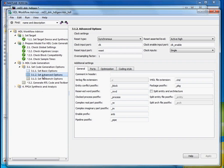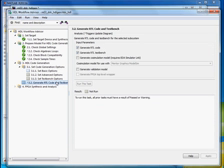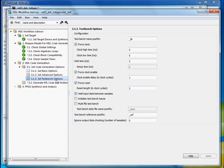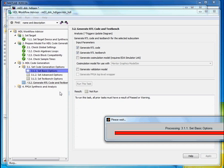So we've got some basic options, including the language you're going to generate, VHDL or Verilog, what sort of reports you want to generate out of this process, so we can get visibility on the way you've generated the code. We have a fair number of options over the form of the HDL, naming of the files, clock signals, and so forth, as well as test bench options as well. So we'll go ahead and do that and start that process and the RTL code generation itself. So we'll get that started and let that run.